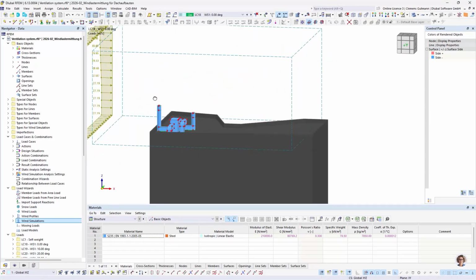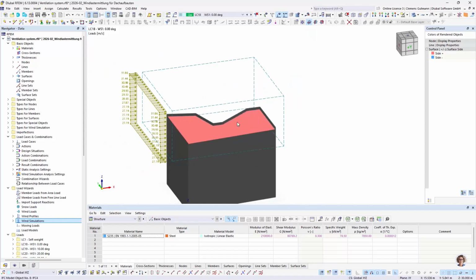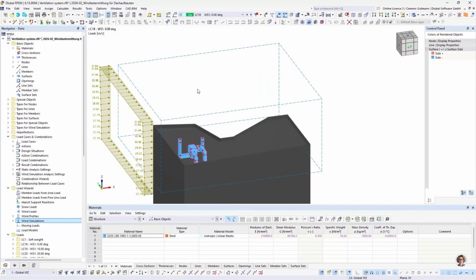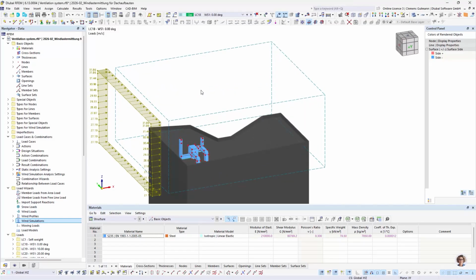And now we have this wind tunnel, and this wind tunnel is a 3D box. And in this box, there's air. And this air has to be meshed so we are able to carry out the wind simulation analysis. That means that we have this volumetric mesh that fills out the box. And the algorithm that creates that mesh now interacts not with the original geometry, but with the shrink wrapping mesh, if it is applied.